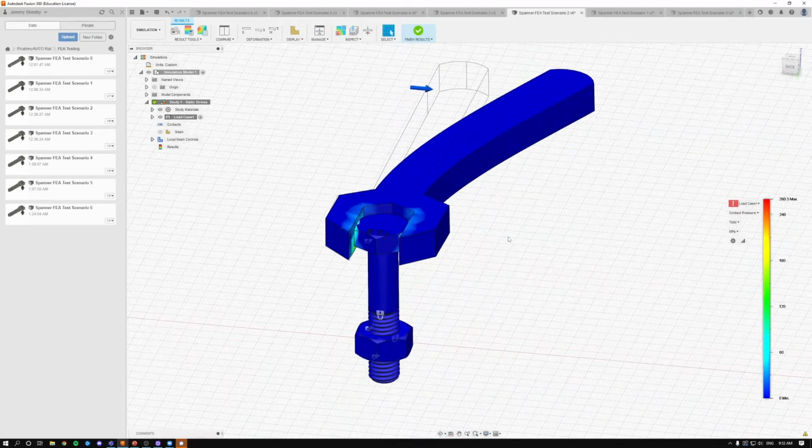And I should just note quickly that setting these constraints is going to have a big impact on the accuracy of your simulation. This is something that everyone who does FEA struggles with, correctly setting boundary conditions. It's nearly impossible to get something that's going to be one-to-one accurate with what you see in real life. I know that through my undergrad, there were plenty of marks deducted for poor boundary condition settings. This is just something that you're going to have to play with the software a lot to get the right feel on how this works. This is far from perfect, but it's just an example.